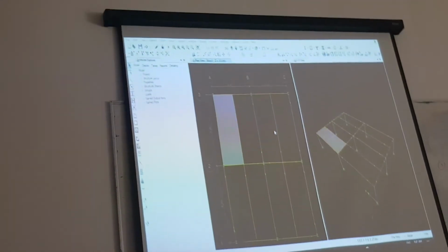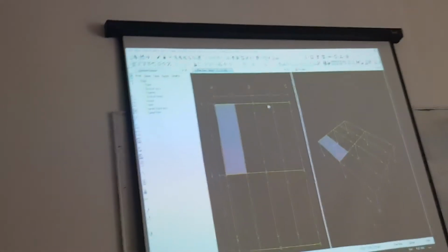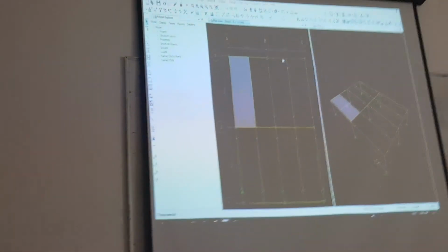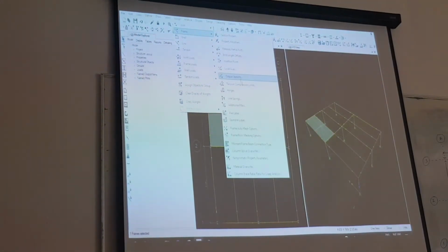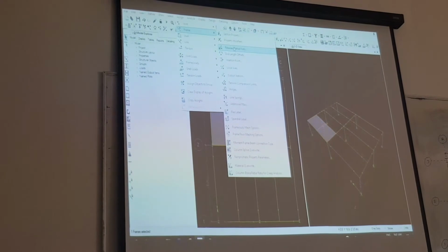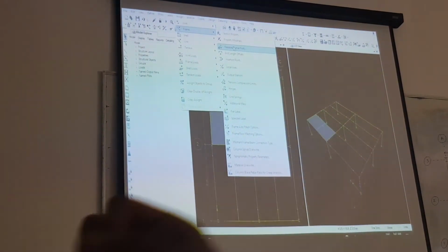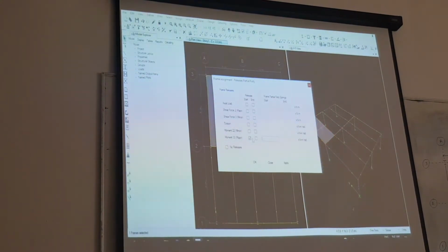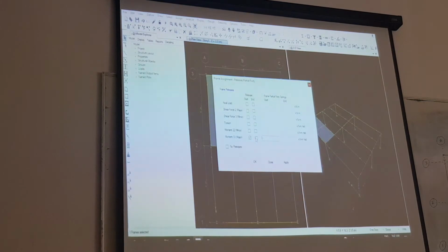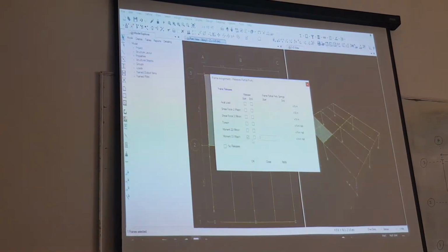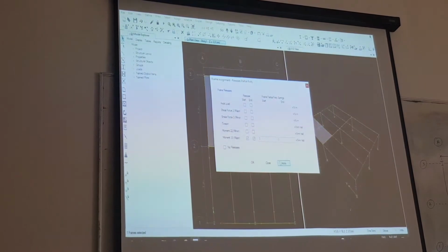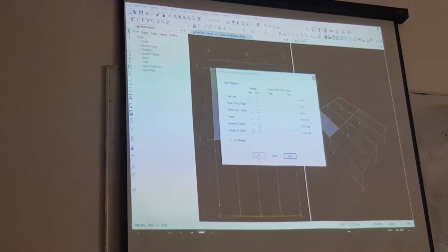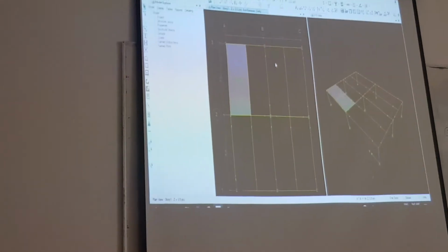If you forget to define those end releases, you are going to select the beam, go to assign, then go to frame, and then click on releases / partial fixity, and then you have to click moment release and click where you are going to provide this moment release, which means start and end, sorry. So click on apply, and then you can see all these joints. Understood?